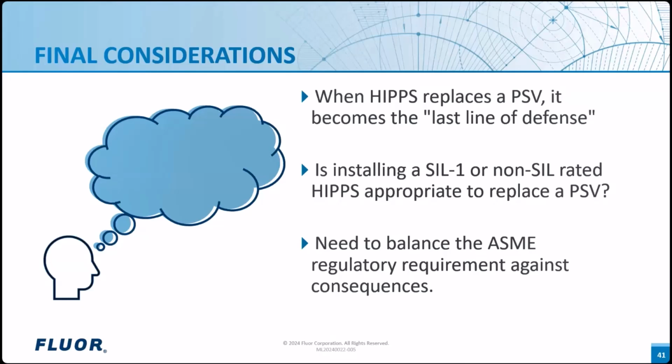For example, a PSV with zero relief load when the potential overpressure is less than 10% is installed. Or, even worse, a PSV is installed when there is no source of pressure that can exceed the design pressure. These examples represent the extreme compliance with ASME code and provide no safety benefit.